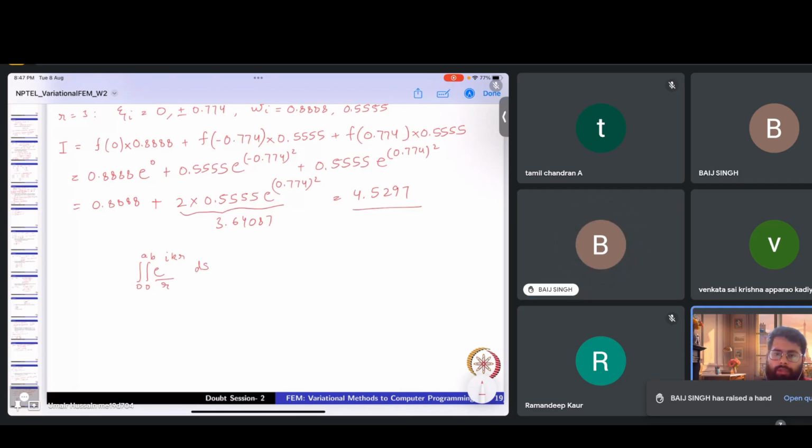What I can recall is that in reduced integration we reduce the number of Gauss points. Now, if we have four-noded elements, it will have a contribution from one of the integration points.